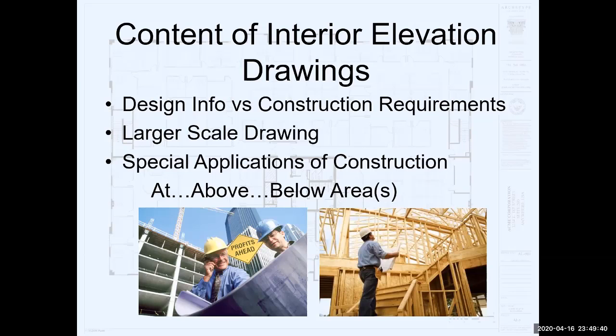And the idea is that we can start to look at the construction requirements from multiple vantage points, not just what's happening in plan view, but what's happening above the elevated wall, what might be happening below in terms of requirements for power, requirements for plumbing, and fixturization. So all those things are pretty important, especially as we're moving into more specific design information.